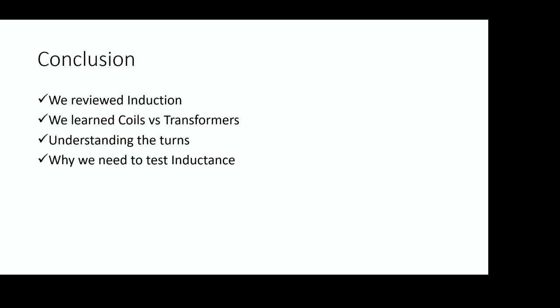So the next phase of that is being able to test it using our standard ET equipment, with a couple of little changes here and there in how the machine might be a little bit different, upgraded after it comes out of the box, but we still can do it. We can do inductance, we can do capacitance, resistance, impedance checking, 4-wire Kelvin, high pot. We're getting all this off the bench now and back onto the machine.